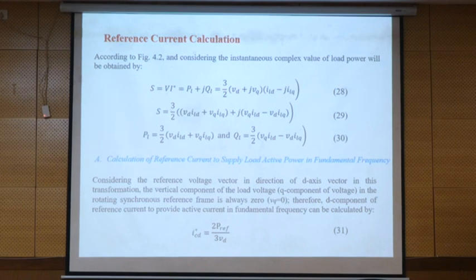Active power in fundamental frequency, okay? Because when we are talking about the fundamental frequency, load cannot be only fundamental. It can be harmonic, reactive, lots of things, okay? So the calculation we calculated from here, that active power can be calculated by this, reactive power can be calculated by this. Apparently we can see Q is equal to 0, here Q is 0.